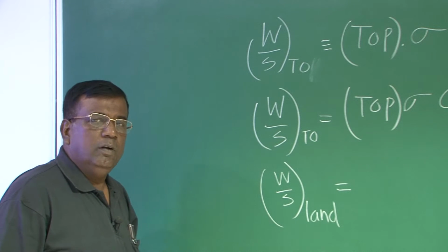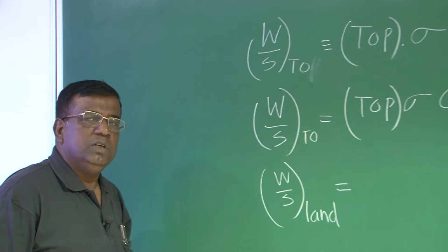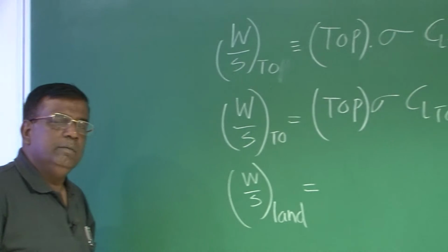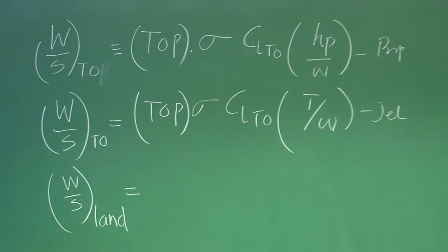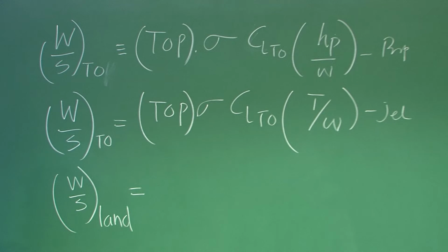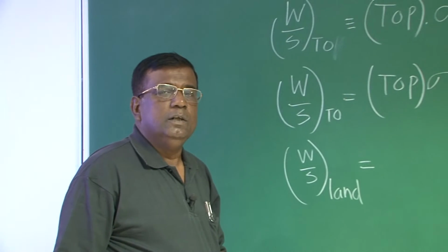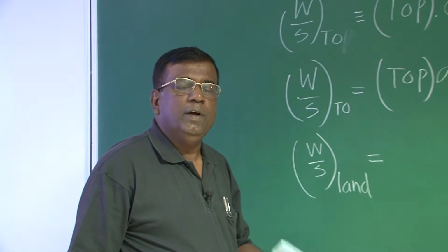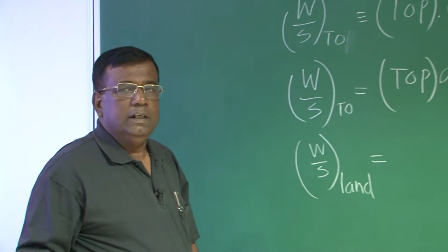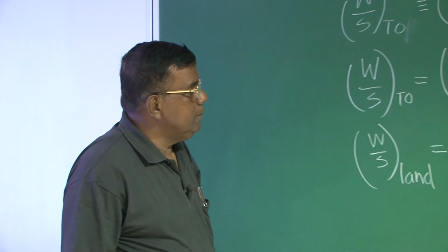Some percentage of fuel will be consumed depending upon what sort of mission it has got. So the weight will change, the wing area remains same. So W by S landing will be different. For many aircraft which are supposed to drop external stores, W by S reduces primarily because the weight has reduced because we have ejected or dropped some stores.